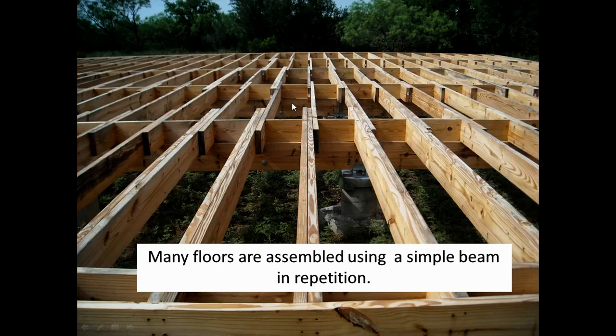So mainly we will use materials that can be loaded in tension as well as compression, and of course one of the ideal ones is timber. And many floors are assembled using a simple timber beam and repeating it throughout the structure. Here's a nice little example of the ground floor being a floor in itself. It's sitting on these elegant little concrete pads every so often, and you can see there's a kind of substructure or beam along here, and then these lateral ones crossing orthogonally from the main structures along that way.